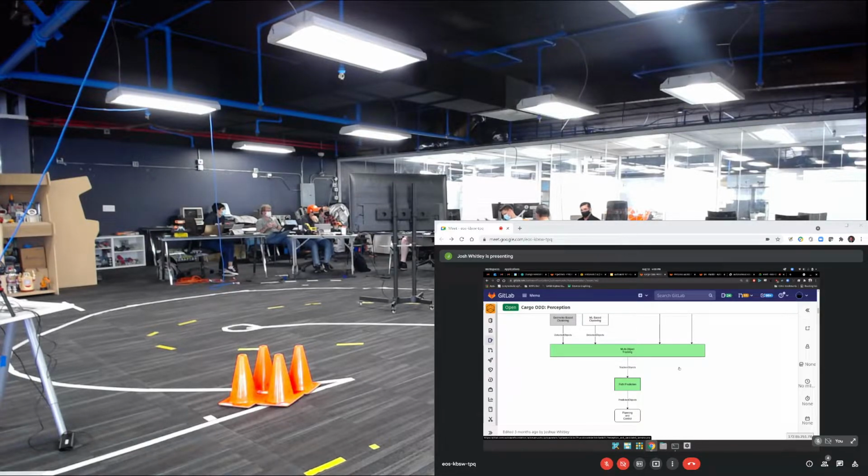Yes, you can, because radars can bounce off the ground and you can get returns from the object in front. But doing that reliably is a lot harder than it sounds. Being able to actually know that the return you're getting in front of the car in front of you is another car and not just an errant return off of some object, that's really, really hard to do. If you had a radar in here facing out that way, you would get reflections outside of the building and under the floor, because RF waves bounce around, right? They don't perfectly penetrate every surface, and they don't reflect perfectly off every surface. So you have to do a lot of filtering.